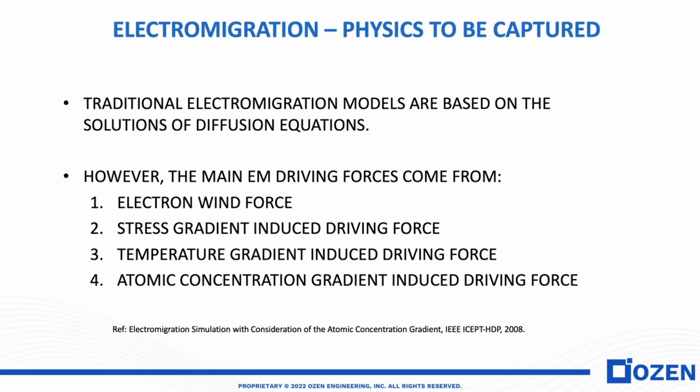But the traditional electromigration models are based on the solution of diffusion equations. Just the diffusion equation. It doesn't take into account all four forces listed here, which are, again, the electron wind force, the stress gradient induced driving force, the temperature gradient induced driving force, and the atomic concentration gradient.